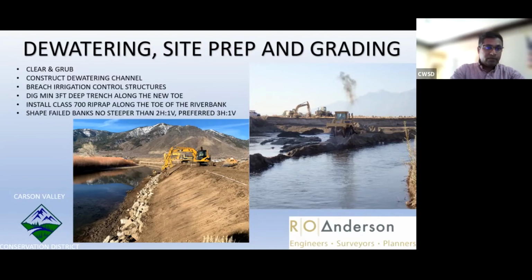Like I said, we dug a minimum 3 feet deep trench along the new toe. So we installed this big rock, so it gives some stability to the new improvements that we're putting in. And then comes the shaping of the riverbanks. We try to stay 3-to-1, but in some places it was not possible.